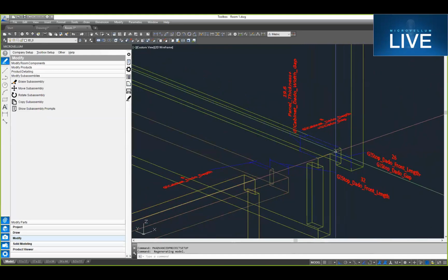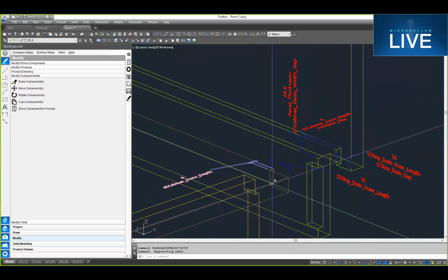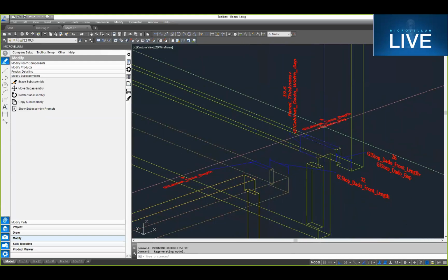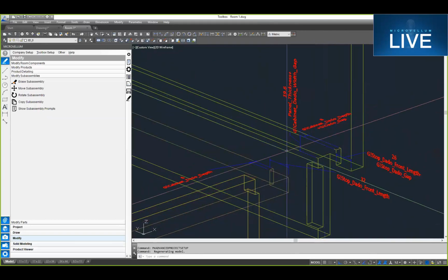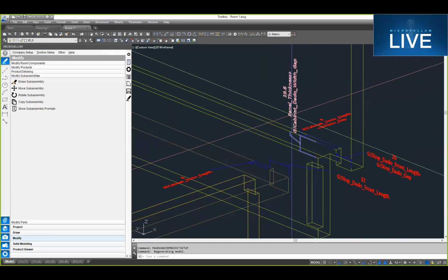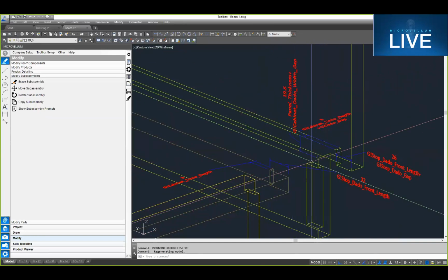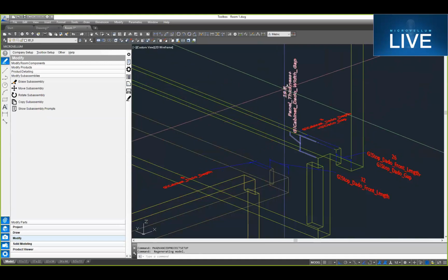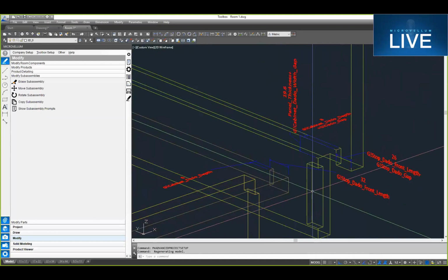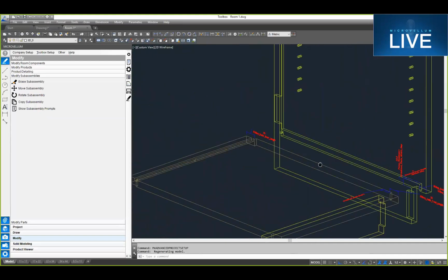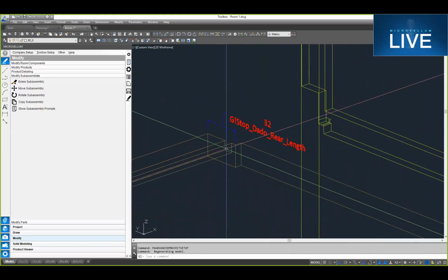And then when we cut our groove, we've got our cabinet dado depth, so this dimension that we're actually putting that part in by, plus the 2 millimeters of our dado depth to give us our dimension there. And then same thing for the width of our dado. We've got the thickness of our panel plus the gap there. So my panel was 19.1 thick, and I had a 0.5 mil gap in there in order to give me the size of my dado. I have the option for a rear stop dado as well.